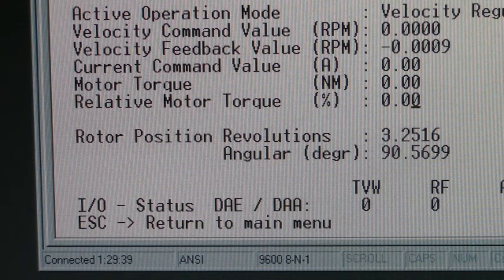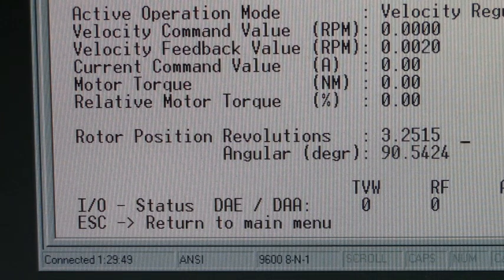Okay, turning off the power supply that's locking the rotor. Now I'm going to move A2 to A3. So we're going to be applying 3 volts to A1 and A3. So here's A2 to the A3 pin.